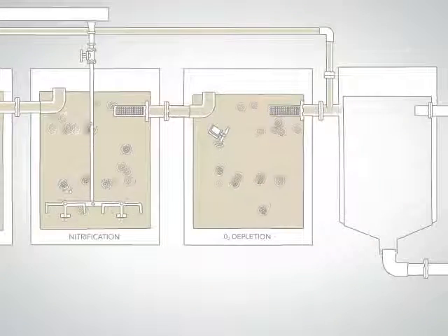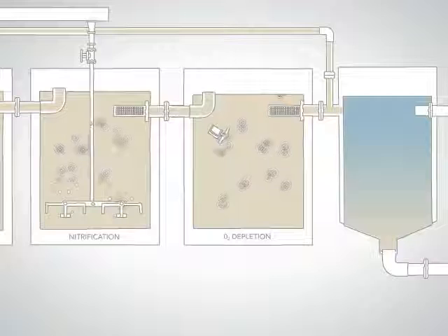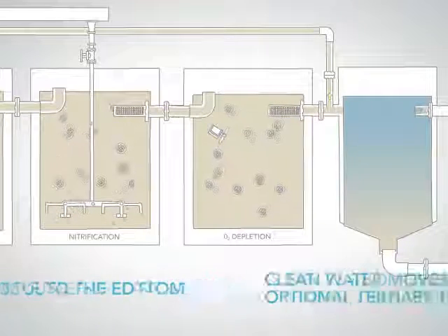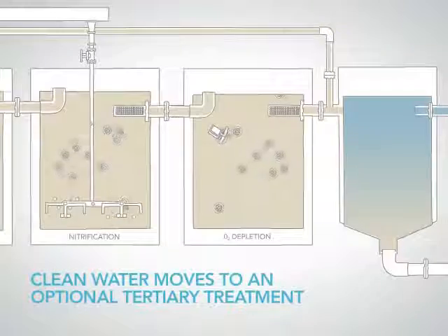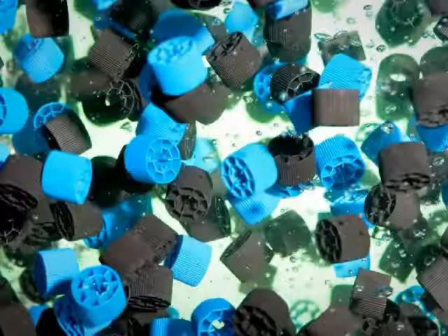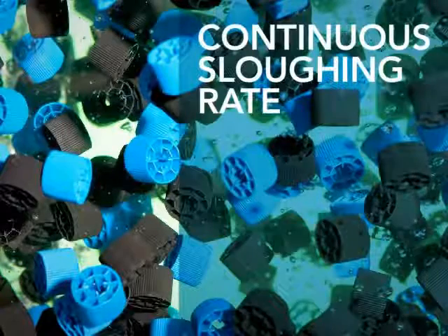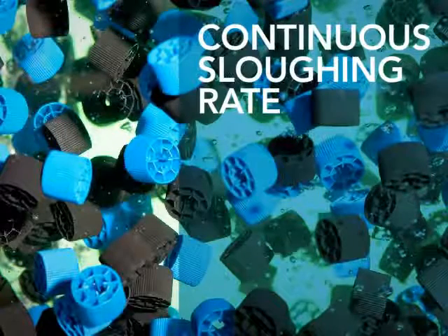After the MBBR process is complete, clarification removes suspended solids from the treated wastewater. At this point, the effluent is ready for any optional tertiary treatment. The Headworks BIO MBBR aeration and mixing processes produce a continuous sloughing rate, which maintains a more active biofilm.